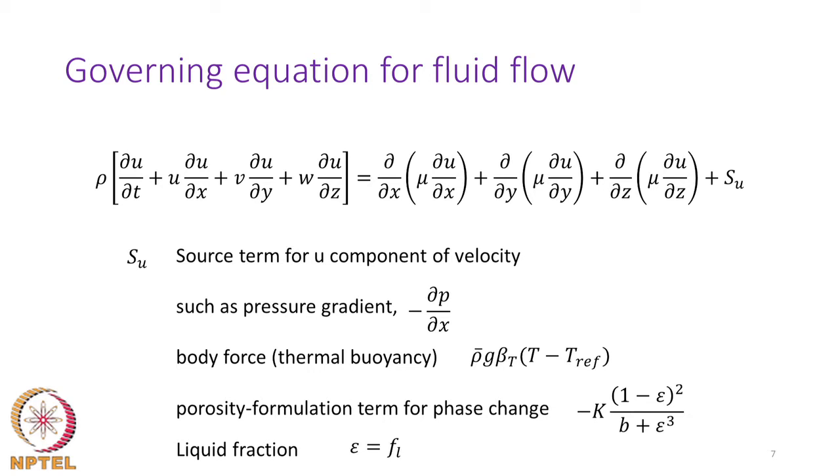So, we have already discussed earlier that we wanted to write an equation that is valid for the entire domain, so that we can have single domain equations, and to ensure that the velocity would go to 0 in the solid, we wanted to use the porosity approach because it is very elegant, and here is the term that we refer to from that approach, and it should also be coming as part of the source term. And here the epsilon I have written as it is from that formulation, it is the same as the liquid fraction, because that is the fraction through which the liquid can flow.